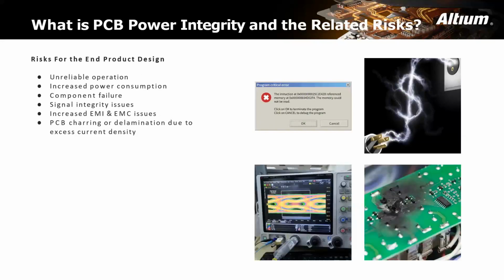Now, what are the risks associated? Well, poor power integrity on the PCB creates many risks in the design. Because of the tighter noise margins and lower supply voltages, power integrity becomes very important. When these margins are exceeded, failures can happen.